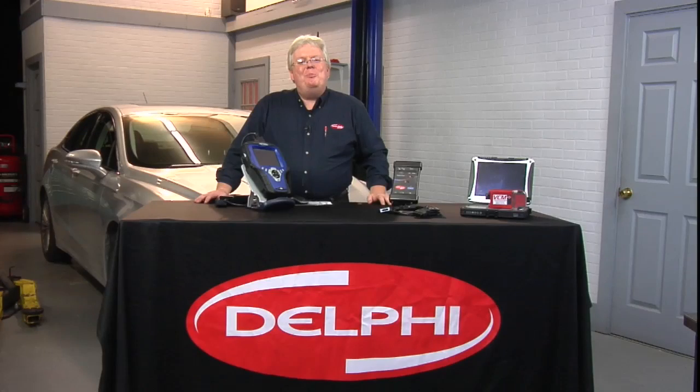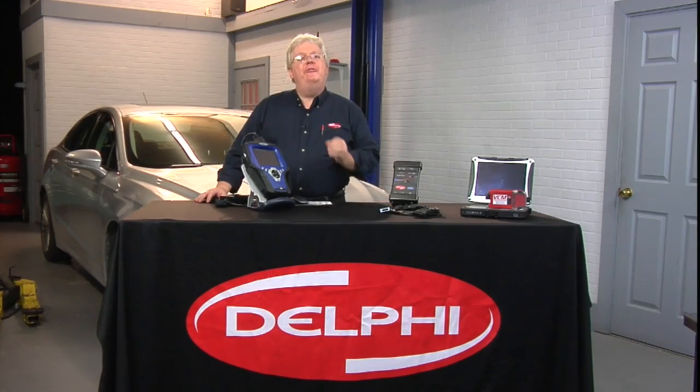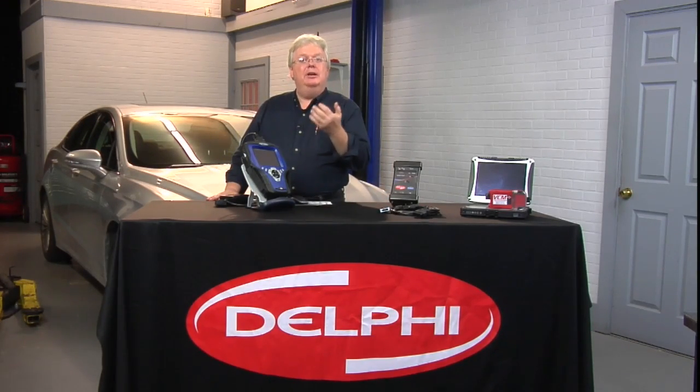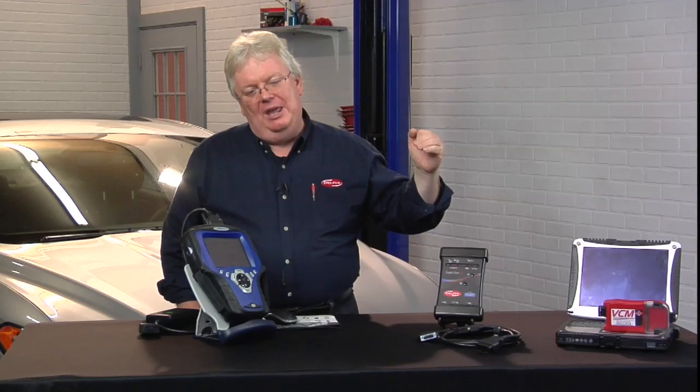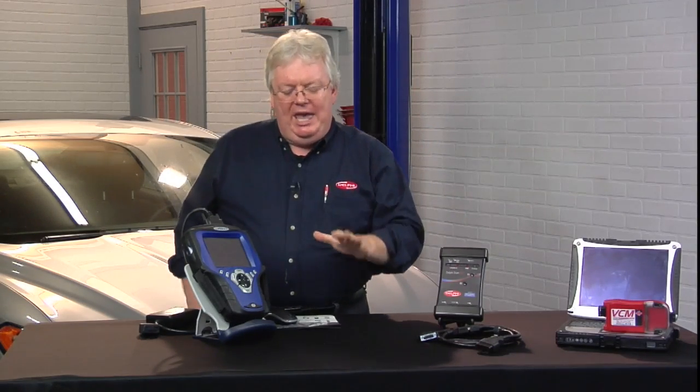He's asking what tools he should get first. Okay. You know, a vacuum gauge, power probe. He really doesn't know what he should start out with. So what are the 5 best diagnostic tools to start out with then? I would get whatever your budget allows for a voltmeter, ohm meter, ammeter, a DVOM, digital multimeter first. That is going to be the biggest thing you're going to use the most often, and arm yourself with knowledge and training to use it to its highest level. And beyond that, I would build my way up from a collection.